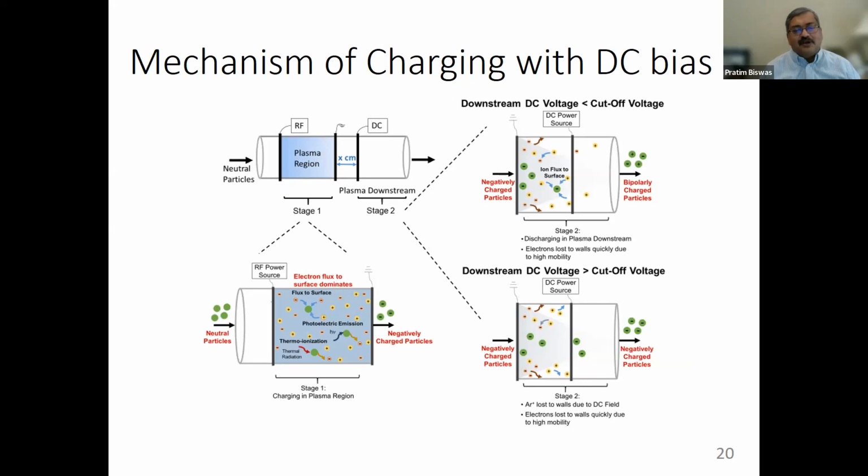So my thought might be first to have a two-stage system to enhance the charges entering the conventional ESP. That may be a first step, because people who are running these systems might not want to disturb their own designs and things that they have to operate. So an approach might be to design a pre-charger, if I might use that term, with a concept like this. And if the flows are high and we need to split it, we could have a series of pre-chargers, just like in the ESP, where the flow gets split into a number of parallel plate zones. So using a pre-charger system would be one thought, but clearly one would have to design this well and actually try it out.